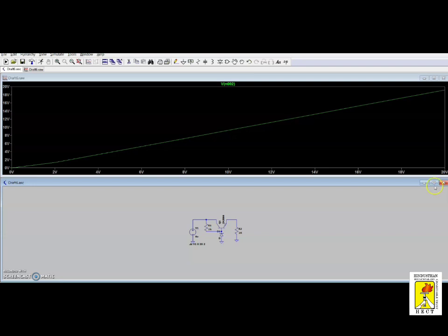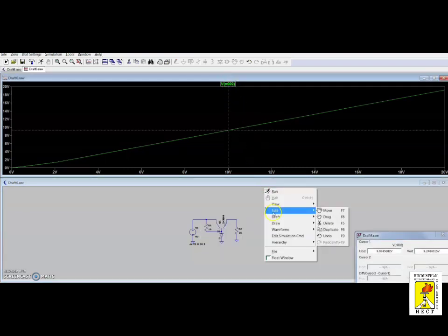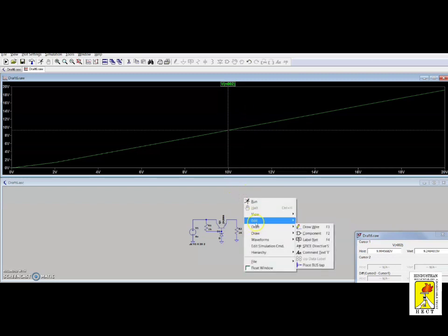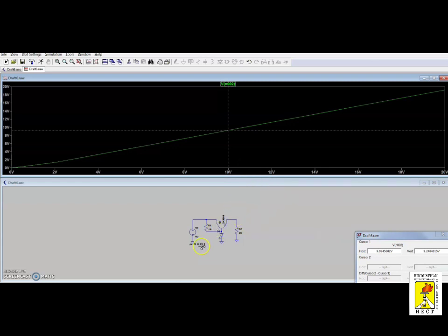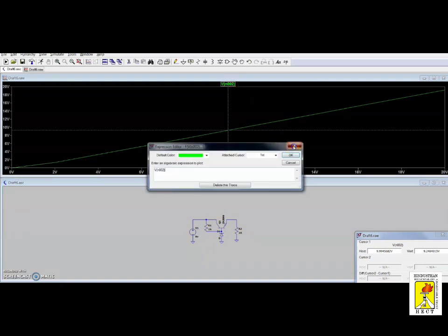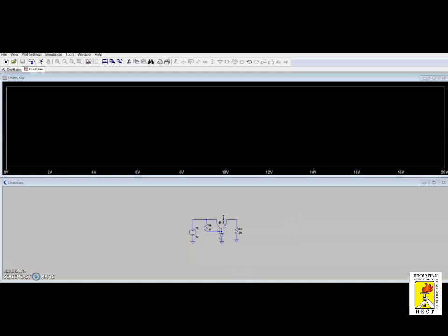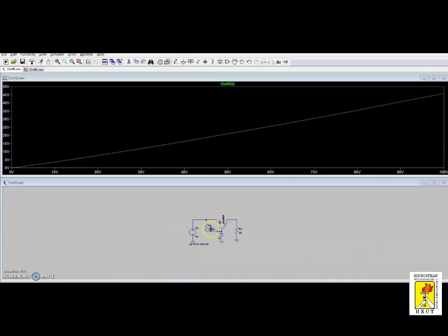This is for line regulation, and similarly if we want to do the load regulation, now we cut this. So now you can look at here. I have changed the resistance value to nearly 500k and changed the voltage from 10 to 100 volt in steps of 10 volt. Then again you can run. By increasing the voltage, the regulator gets regulated nearly at 45 volt, a constant value.